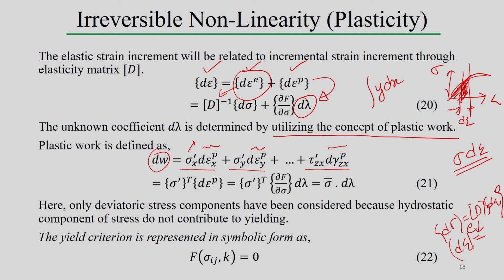So, that can be represented finally in this way also, but in this case we have considered the sigma x dot. That means we have considered only the deviatoric stress component. Why? Because in the plasticity law, even if we look into the von Mises yield condition, once we try to develop it, remember we discussed this relative to the stress analysis part also.